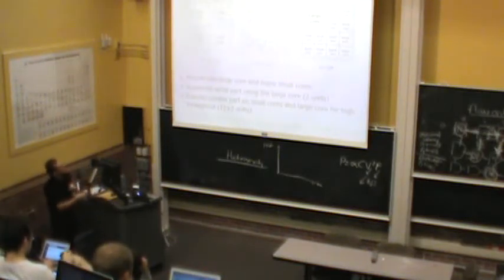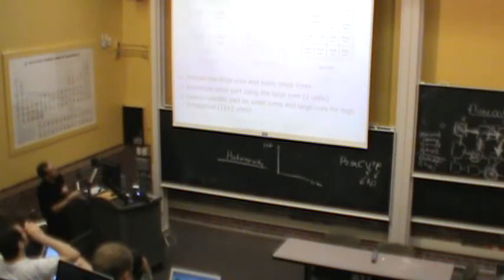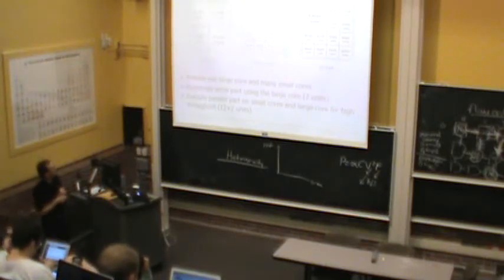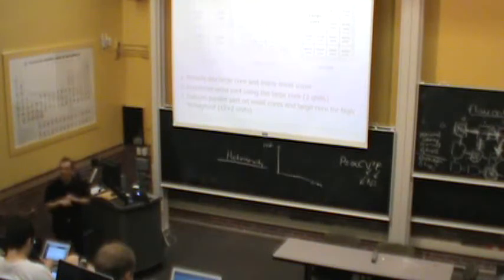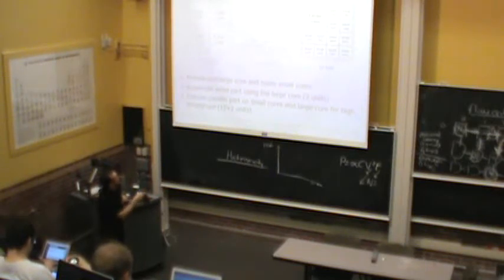And if you look at it, this is an asymmetric multi-core processor. You have 1 large core that occupies 4 units of area, and 12 small cores that occupy 12 units total of area. Now, in the serial portion of your program, you get the performance of this tile large approach, right? You get 2 units of performance. In the parallel portion, you get 12 plus 2 units, 14 units. Because you can execute 2 threads here. Well, the performance of one thread will be 2 over here. Or you can time multiplex down to get 2 performance.